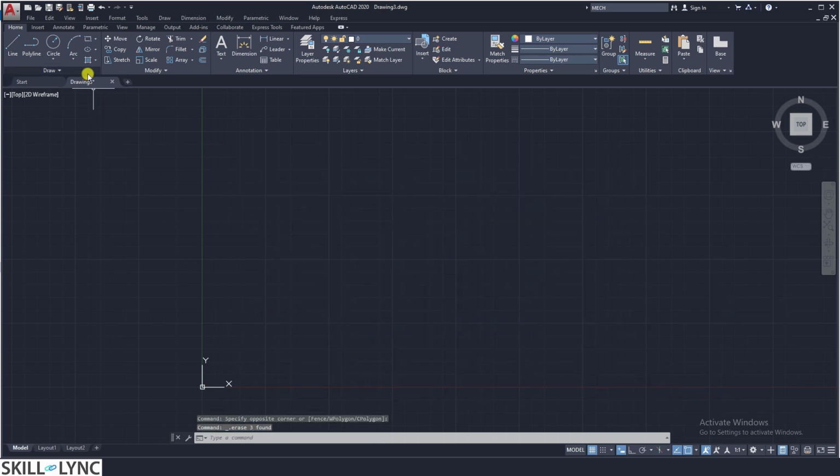So next is the drawing of a polygon. The polygon can be invoked by the command POL. The first prompt is the request for the number of sides of the polygon. By default the number of sides is prompted as 4, and we can choose whatever we want. Suppose the polygon has 8 sides, and then specify the center of the polygon or the edge of the polygon. We have two options.